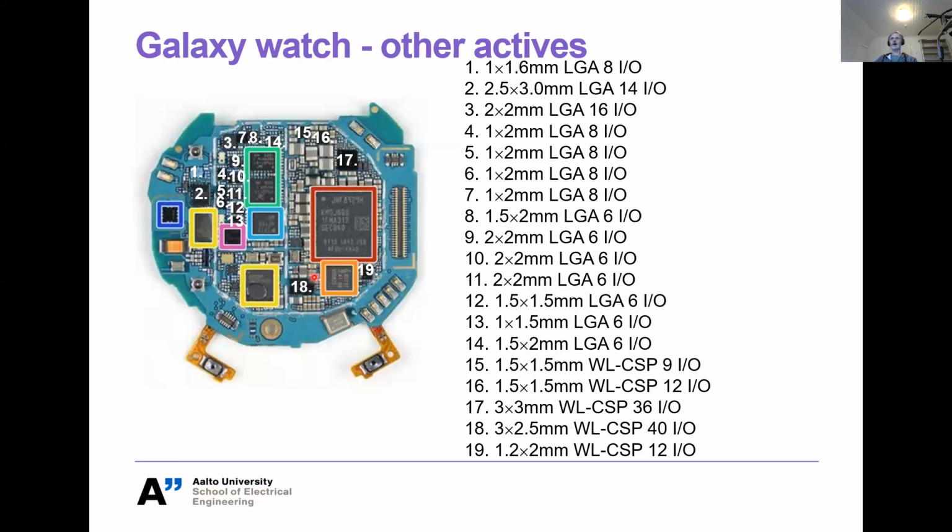So basically one quarter of a millimeter times one eighth of a millimeter. So at least with my old eyes, I really cannot anymore see the smallest components there without a microscope. So you can also think that if you would need to replace, for example, this specific component here, where the size is a fraction of a millimeter, you need to desolder it, and then you need to apply the new solder material and then apply a new component and solder it back.